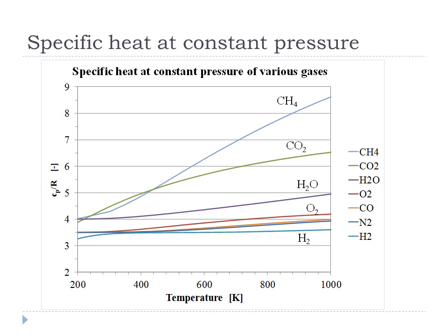Then as you increase temperature, hydrogen really doesn't change, but oxygen, nitrogen, and carbon monoxide start changing slightly, and if you continued, you would actually reach about 9/2 R, which on this graph is 4.5. But we haven't gotten to a high enough temperature.